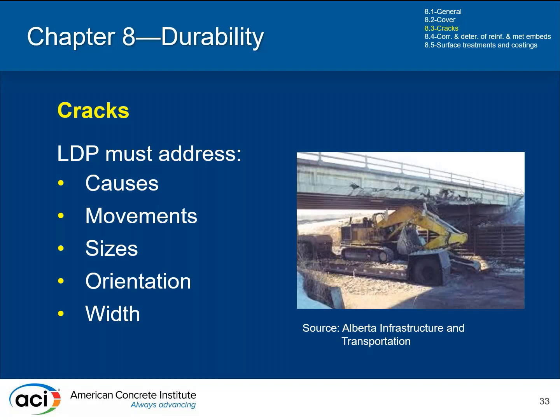You really need to start thinking about why you have a crack and what it is doing. You need to think about what caused it. Is it going to move? Is it size, orientation, its width? What are the characteristics of the crack? You must understand that, and the code needs you to consider that, so you can understand its impact, so you can figure out the right way to deal with it and what is the right approach.